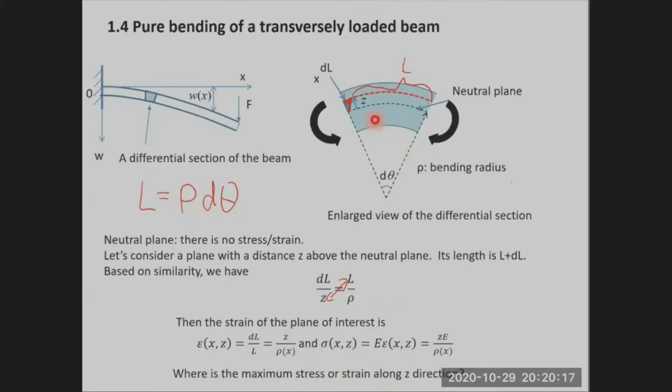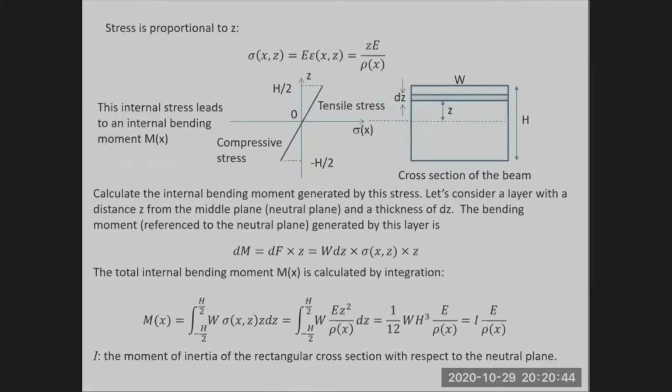That's why when we bend a stick, it always cracks on the surface first. So this result is consistent with our everyday life experience. So the stress is linearly proportional to z, a linear function of z.